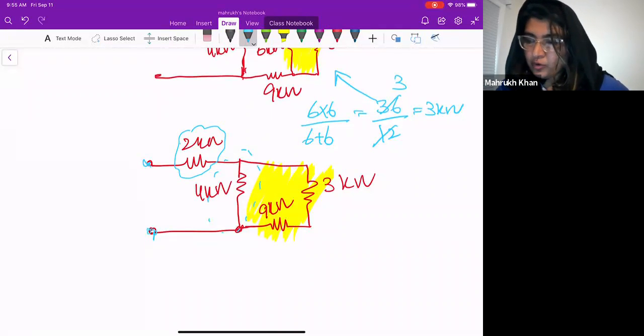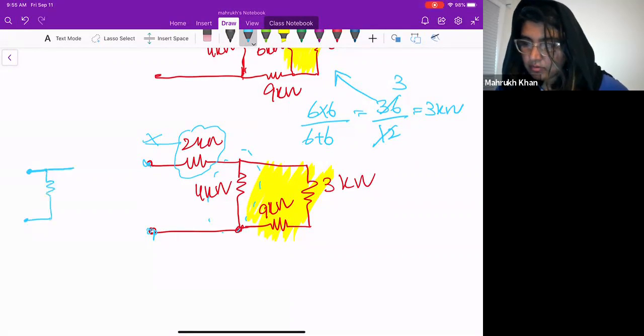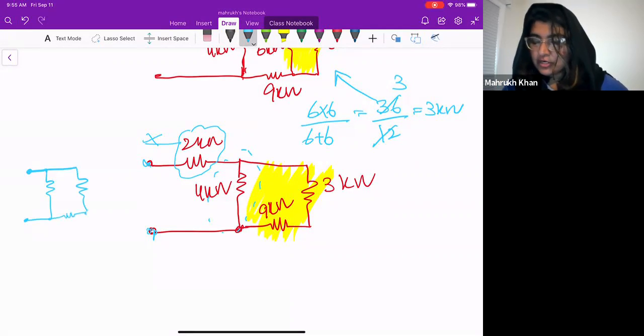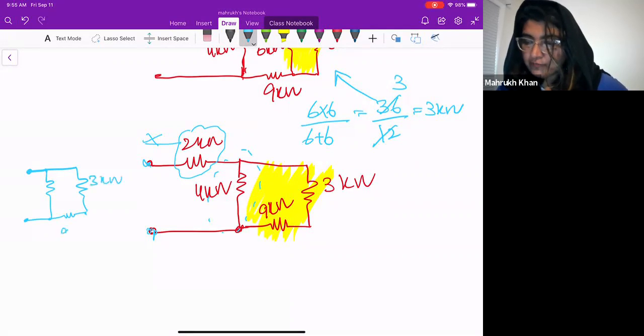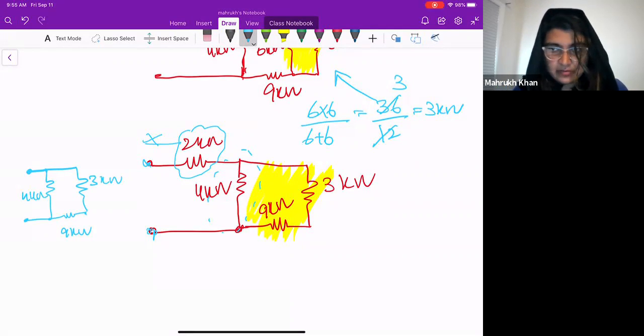If this 2 kilo ohms was not there, then you can draw this circuit as so this circuit shows that you are trying to measure the voltage across 4 kilo ohms, but all three resistors will be in series, right?